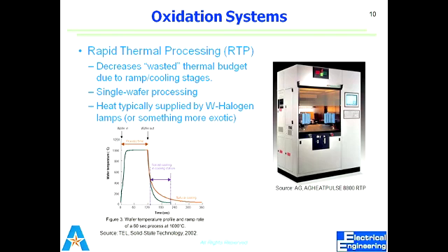When you cool it down from high temperature and when you heat up to high temperature, due to the difference in the thermal coefficient of expansion, there would be a stress as well. So this is very slow actually. It takes much time for the wafers to heat up to 1000 degrees centigrade, and it takes much time for the wafers to cool down from high temperature to low temperature. So that's why our thermal budget would be very high.